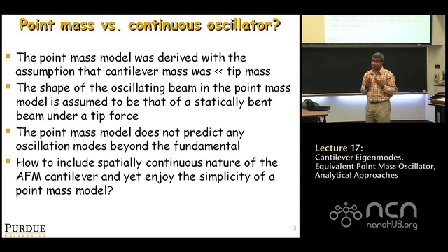But if you think about it, if we say that this cantilever acts only as a spring, that implies you're neglecting the mass of the cantilever. You're just saying the tip is there and it is suspended by a spring. So you've completely neglected the mass. You represented the cantilever as a spring and forgotten about its inertia, when in reality the cantilever mass is much more than the tip mass.